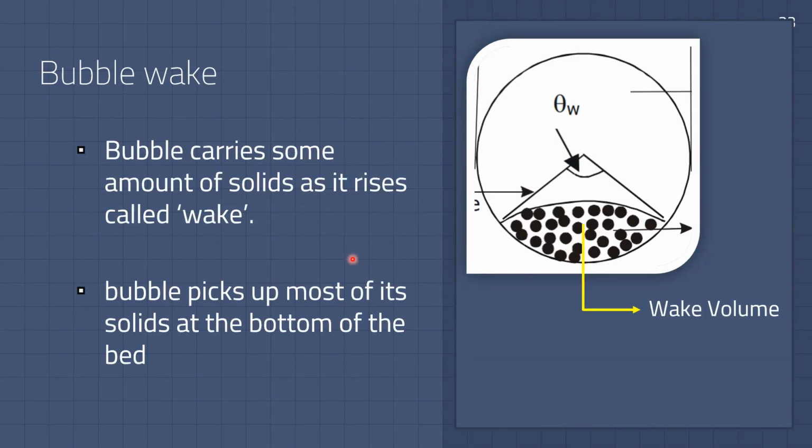When a bubble rises, it carries some amount of solids inside. This is called wake. The formation of a wake follows directly when the bubble forms. Hence, the bubble picks up most of its solids at the bottom of the bed as it leaves the distributor plate.